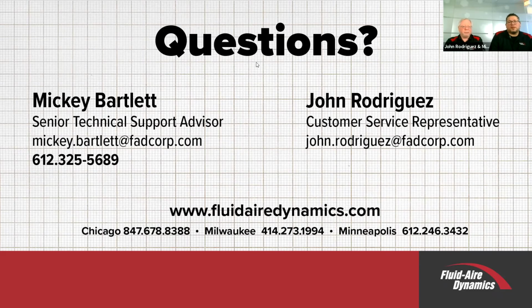So Luis, you do have another question here as to how to set up the equipment in the compressor room, distance from the walls, how to pipe. I'll be very honest, that's a question we could take all day just answering. Everybody asks for 3 feet around all your pieces of equipment, and we know that sometimes compressor rooms aren't that large.